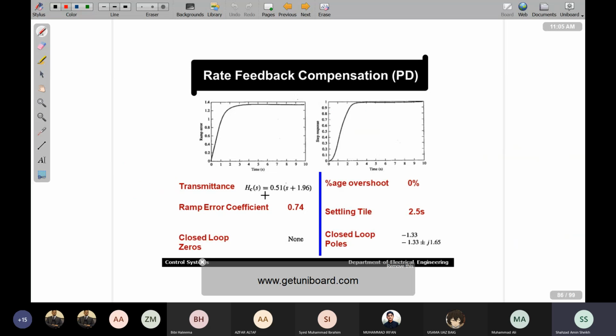So here we are stopping our design procedure at K is equal to 6. At K is equal to 6, we have A is equal to 0.51, where we had obtained our maximum relative stability. And so in this case, our GCFS was 1 plus 0.51s, and you can write this in this form as well. If you take 0.51 common, then it is s plus 1.96, the location of the closed loop zero, that is minus 1.96, which you will place in your system. Any questions?